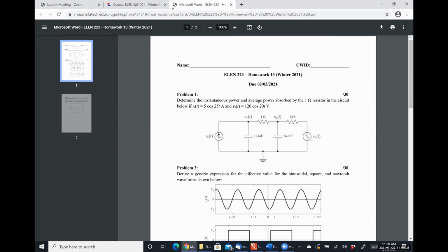Yeah, and you can't do that because these are operating at different frequencies. So you cannot compare Vx at one frequency to Vy at the other frequency. It's like comparing apples and snails. It's not even a fruit, it's way off. So yeah, that's a common mistake, and that's what makes these types of calculations so tedious, and which spurred the creation of complex power, so you don't have to worry about all that.